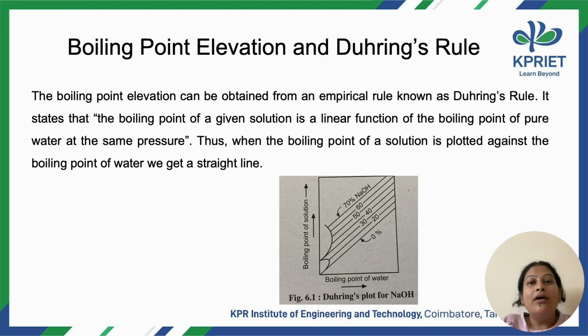So in this lecture, we discussed what evaporation is, and the importance of evaporation in heat transfer operations when compared to drying. We discussed how an evaporator is normally evaluated, for example by making use of the capacity and economy concepts, and also methods of improving the economy of the evaporator by using multiple effect evaporators, and this concept of vapor recompression systems. We had a clear idea about single and multiple effect evaporators. Then we moved on to boiling point elevation and Duhring's rule.